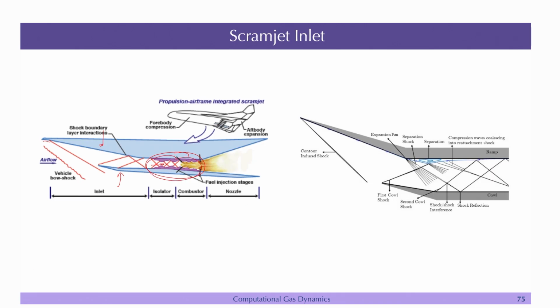And secondly, how does the shock or the flow which is coming from this side basically interact with the modular, right. So, as you may guess that, okay, there may be separation here. Okay, there is an expansion fan, there is a separation, and because this shock is impinging on this, this leads to separation, but very close to that you have this expansion, and there is another expansion on this also. So, it is a very complicated phenomenon of shock interaction, shock expansion fan interaction, shock modular interaction, and it is a challenging problem for any CFD solver. Okay.